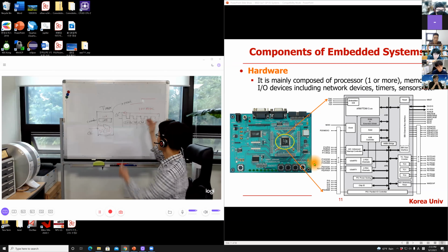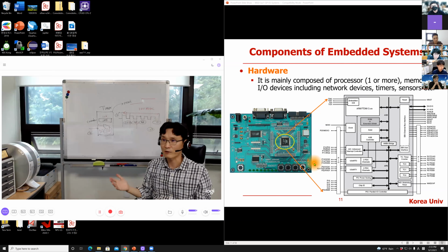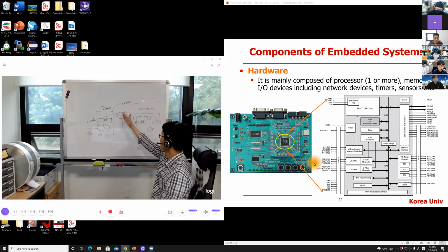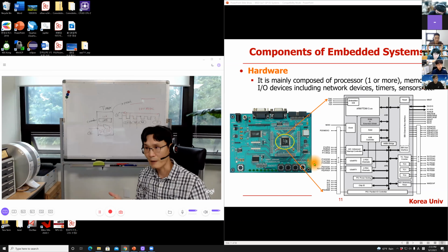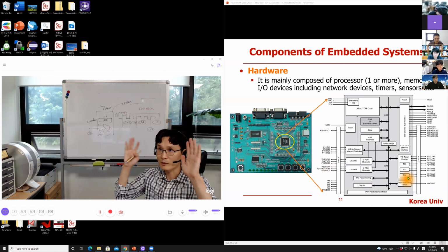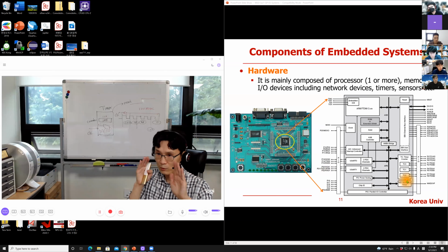So within 100 millisecond, if you don't refresh this register, then that means something is wrong with what you designed. If everything goes fine, then before this number goes to 0, this register will refresh it to some non-zero value. If something goes wrong, that will happen. So watchdog timer is used. Watchdog, right? Think about that dog. Keep watching the system. Think about the meaning of this word, watchdog. Keep watching the system, right? Something goes wrong, then reset, right?